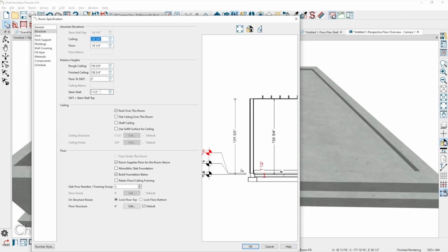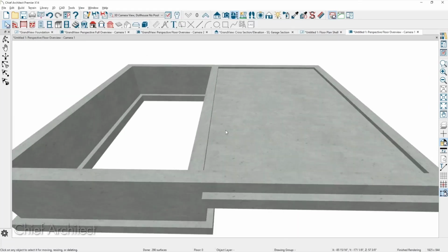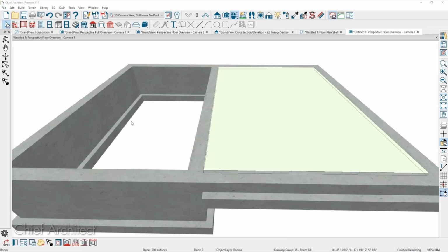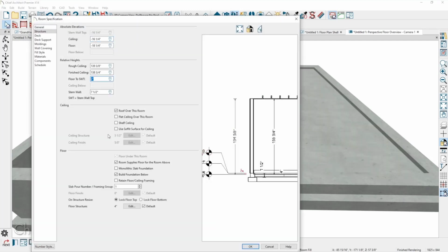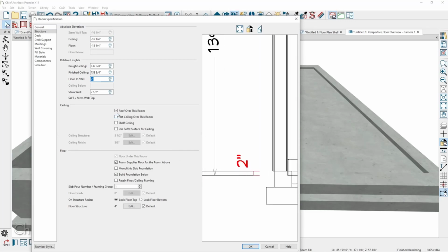Well, yeah, I don't want the top of my garage foundation to be above the house foundation. Right. And so in this case, it's very close. I think, what is it? 3.5 inches, 2.5 inches, right? Yeah. If we zoom in there, that's 2 inches below. So if you want it to be, let's say, 12 inches.